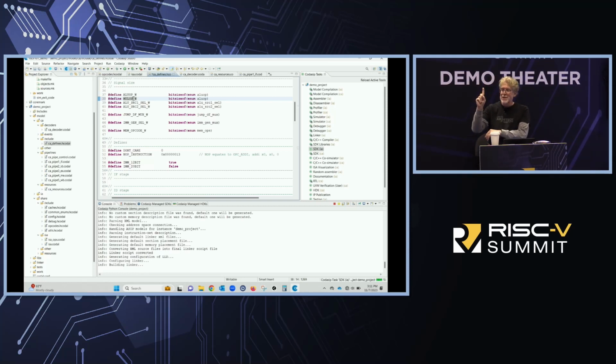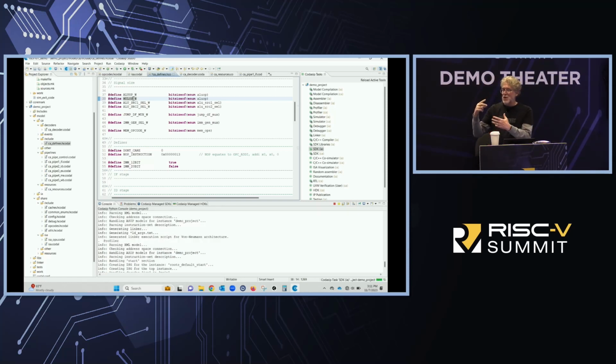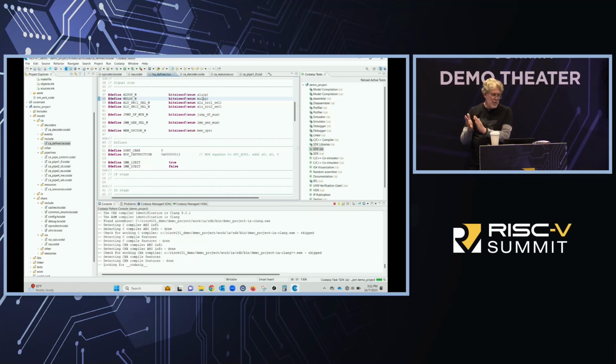So really I only need one signal right now. But if I all of a sudden add support of the upper 64 bits, that would be a different opcode, and then all of a sudden I would need two. Now we're going to write this code so that as I add more micro opcodes to this compute element, I don't have to go back and manually change the width of my signal. We'll do it automatically. So you can see I've created this new definition, mul op, and I'm going to have to tell it what to do the ops sizing with.